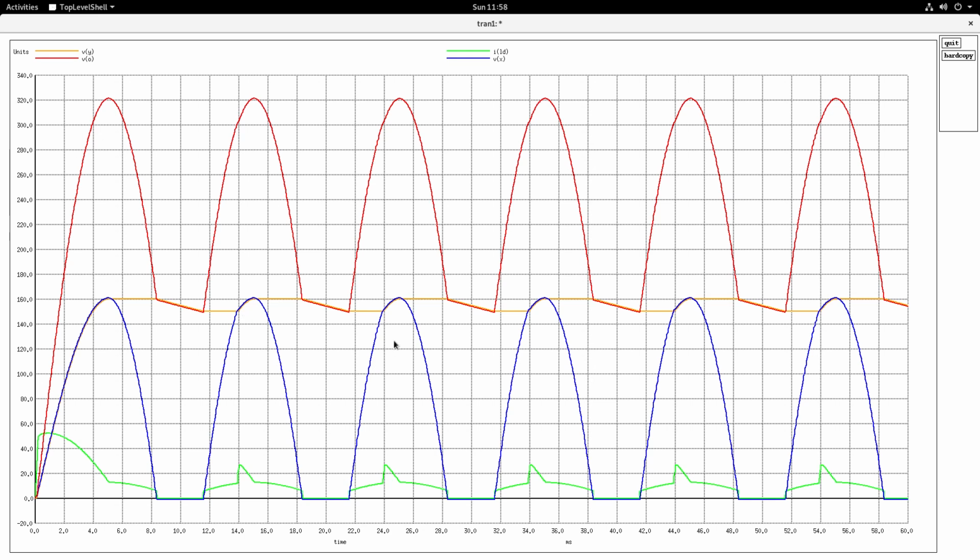So I will enclose this circuit also as a resource for you, so that you can work on it and try to understand and get as much insight as you can about this circuit. The basic takeaway is that we have introduced a current wave shape with a larger conduction angle, thereby reducing significantly the peak current and thereby improving the power factor. But all this is at the expense of an output voltage ripple which is very high.